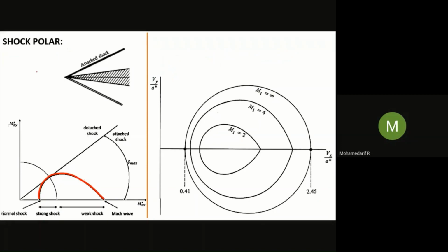So for example, I am taking Mach number 2 and initially theta of 10 degrees. Now see how to calculate M2 from this graph. This is the Mach number 2 graph, right? This line alone I have taken here. Assume other lines are there; I have taken only the Mach number 2 line. And this is the sonic line. So Mach number 2 I have taken, and now the theta is 10 degrees.